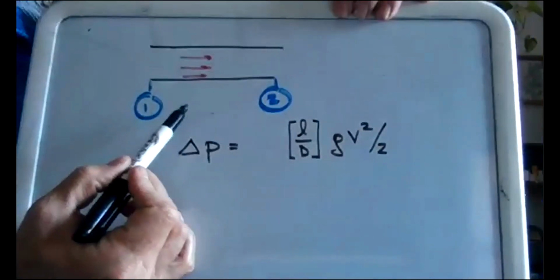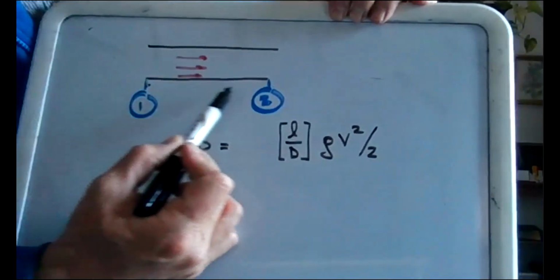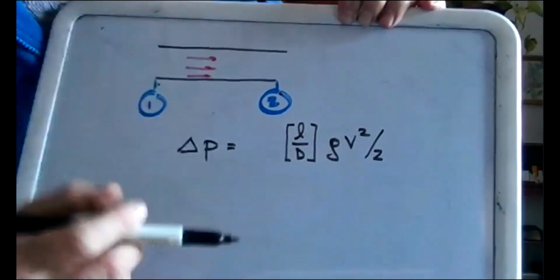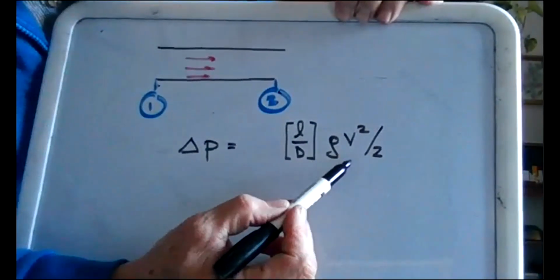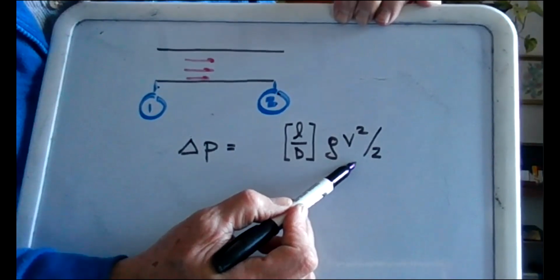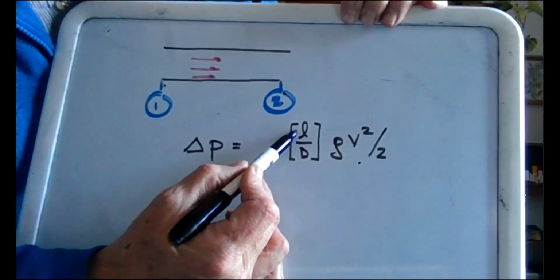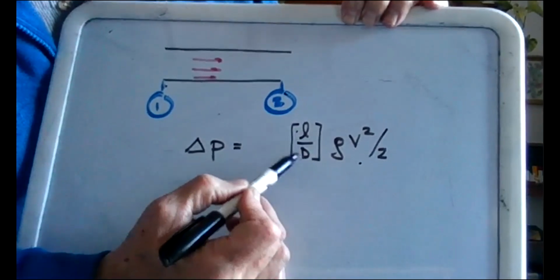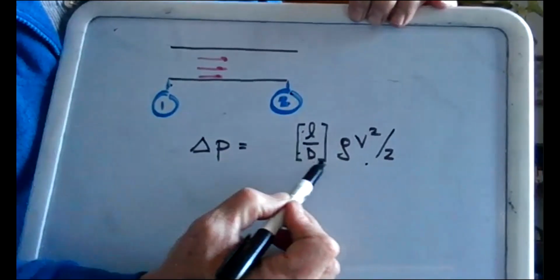But once again, it is a very important problem in engineering to figure out the pressure loss of a fluid as it goes from one point to another. It turns out it has been very productive to think about it as coming from an energy term, how much energy of motion the fluid actually has. It's proportional to the length, the longer the pipe is, the greater the pressure drop, and inversely proportional to the diameter. Engineers wanted to think about it that way.